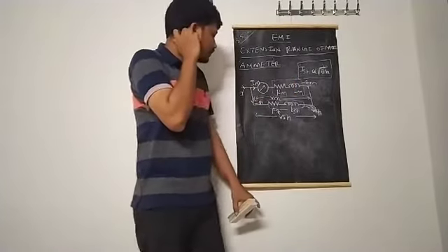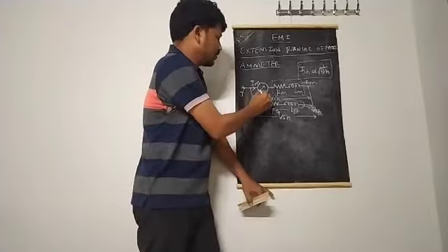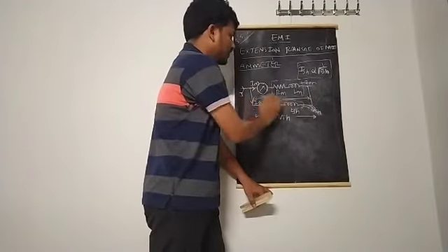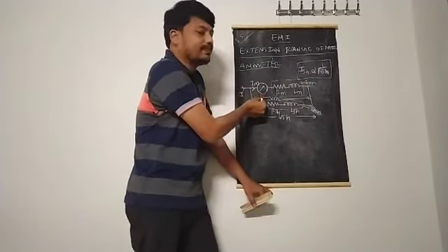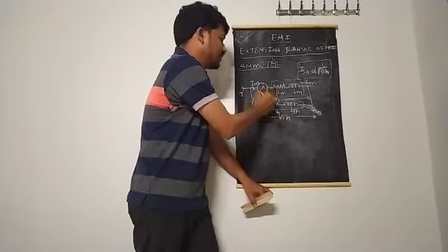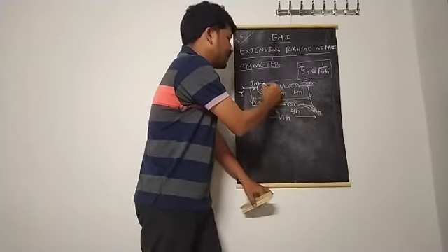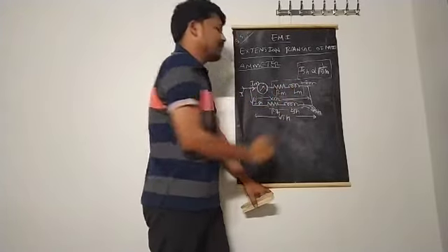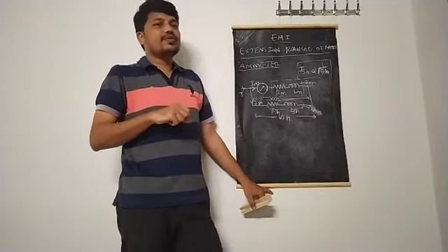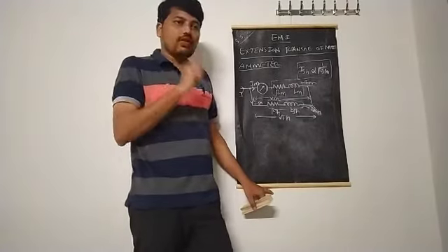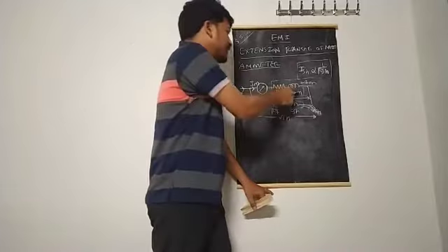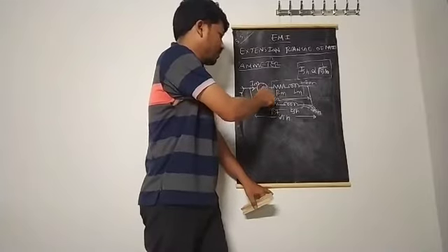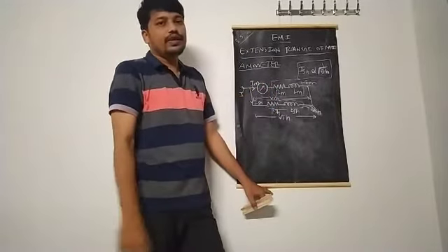So initially, for the meter without extension, this is the equivalent circuit. Look only at the upper part, leave the lower part. This is IM, the meter indication needle, that is the symbol of the meter, and resistance RM, the internal resistance of the meter, and LM, the inductance of the meter. In a moving iron instrument there is a coil and an iron piece. The inductance of the coil is LM and the resistance of the coil is RM, and we show the meter as a circle with an arrow mark. This is the existing meter.